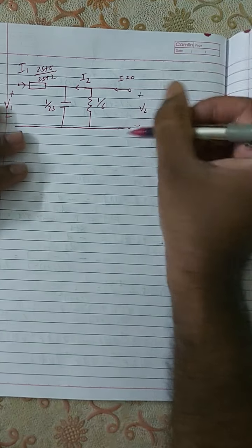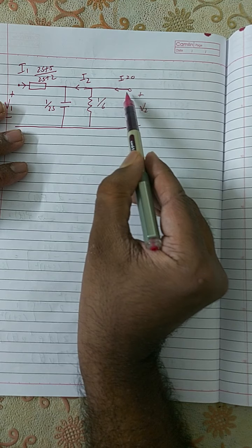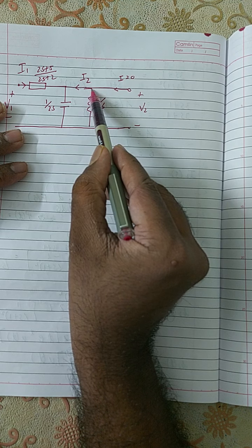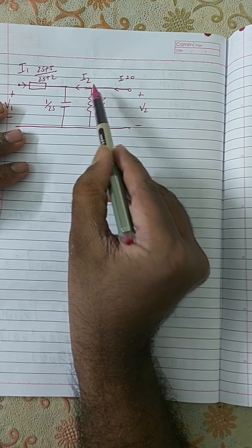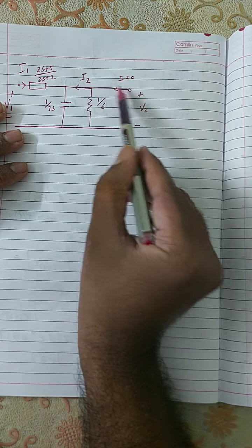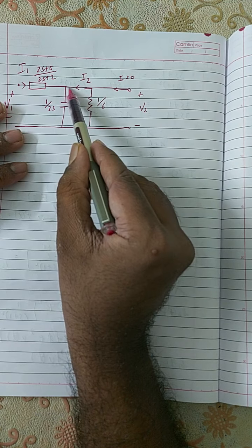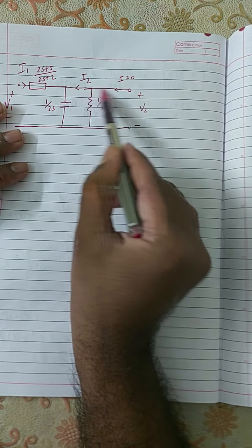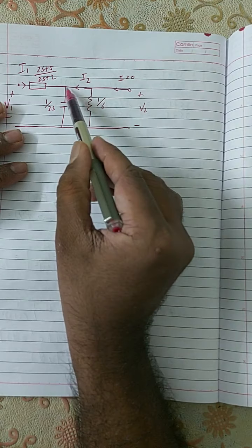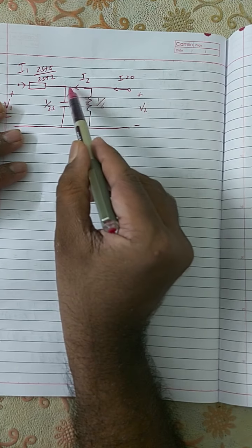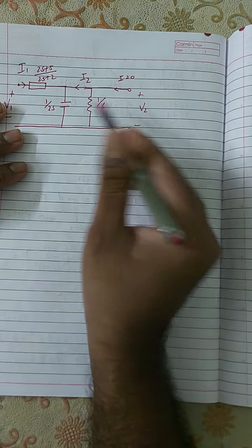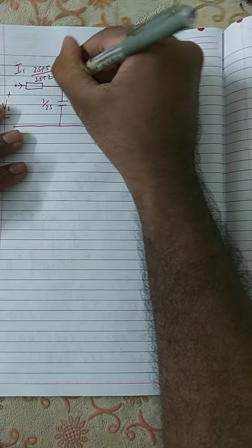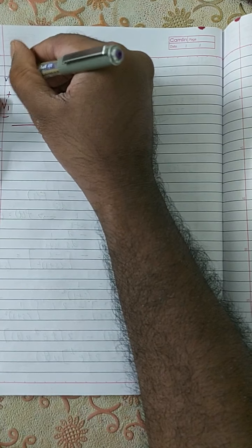If you look very carefully over here, this is V2. See, there is no element over here. So if this is V2, then this is also V2. So this entire wire that you see here is actually a single connection because there is no resistor or capacitor or anything in between. So this entire line is actually V2. I can mark this as V2, this is V2, this is also V2, and this is V1.